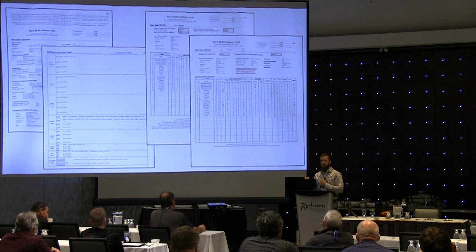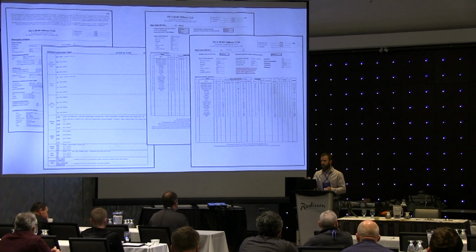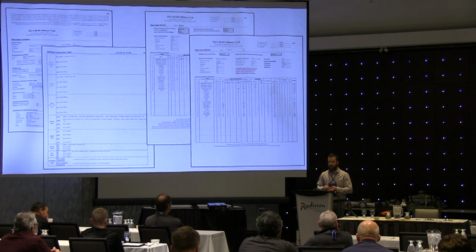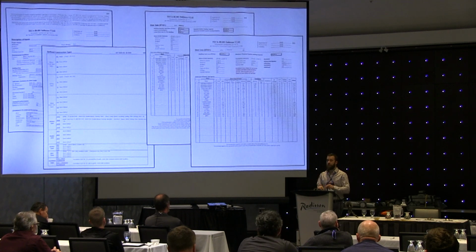So in the software, we just display climate zone for you. Nothing's going on in the background with climate zone specifically. That's just if you need to look at your climate zone to see what the code requires for code minimum insulation values, for example. That's just for your information. If you're in one of these areas that technically is climate zone 4, but because of elevation it's climate zone 5, you would just have to input custom temperatures and wind conditions on your building to best model the environment.